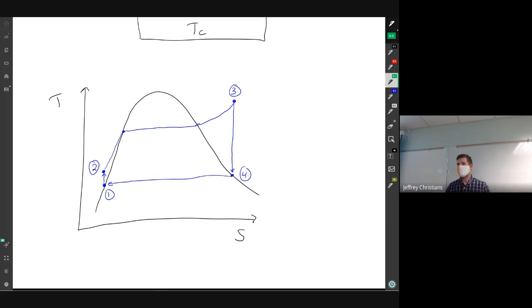When you go through and look at the temperatures in the system and compare a Carnot cycle to a Rankine cycle, a basic Rankine cycle like this is really bad. So there's a lot of extra work that we have to do to say, how can we get from this? We can design all the equipment now, which is good. Like, we can actually do it. But how do we get closer back to a Carnot cycle? There's a lot of modifications and thought that goes into how do we make something that looks like this? How do we take it and make it more square? What kind of modifications, what extra steps can we add in order to do that?